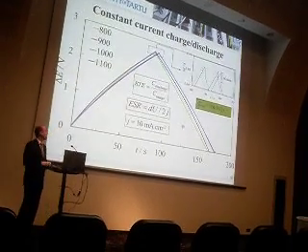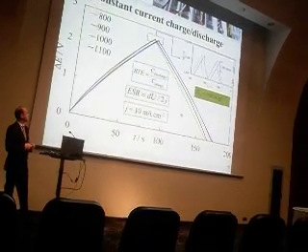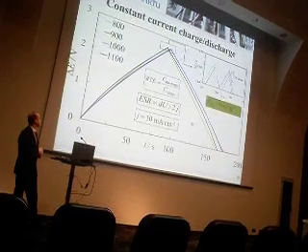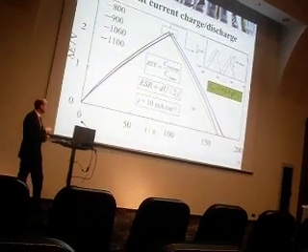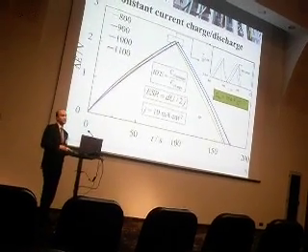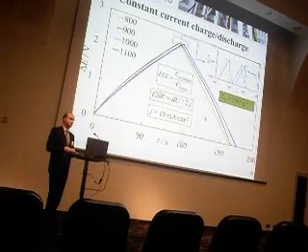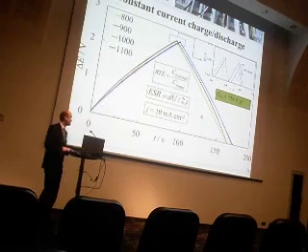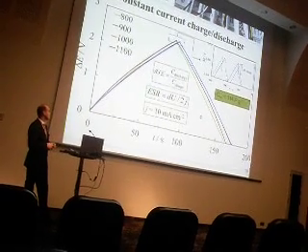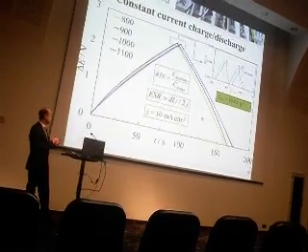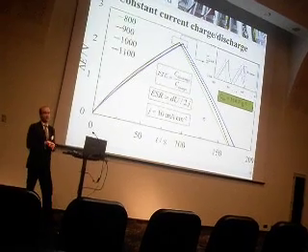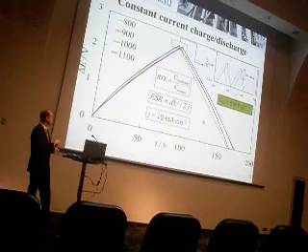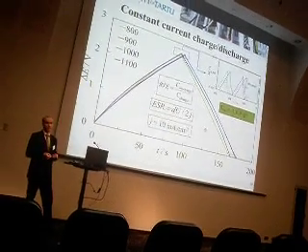We also carried out some constant current charge-discharge measurements, and from these measurements we calculated the round trip efficiency to be about 98% for all materials. And again we saw that the synthesis temperature did not affect the capacitance of the material very much.